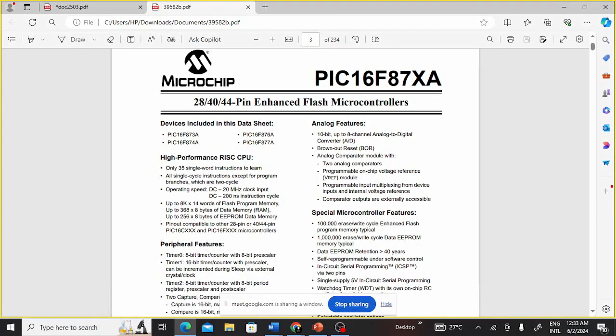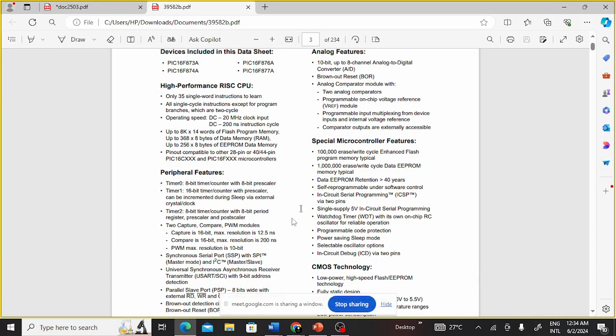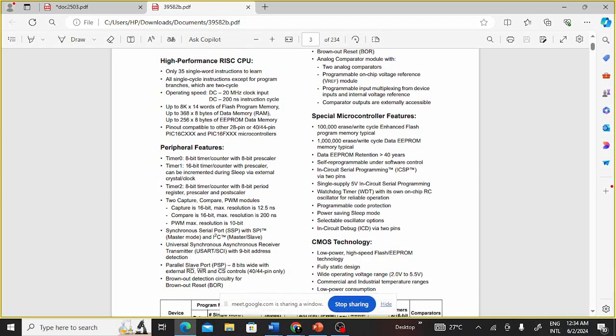So not really all. So timer 0, timer 1, timer 2, let's quickly look at it. Timer 0 is 8 bits, timer 1 is 16 bits, and timer 2, you can see that one thing you will see again is that the datasheet of PIC tends to be more robust than the datasheet of ATMEGA. Let me show you something.